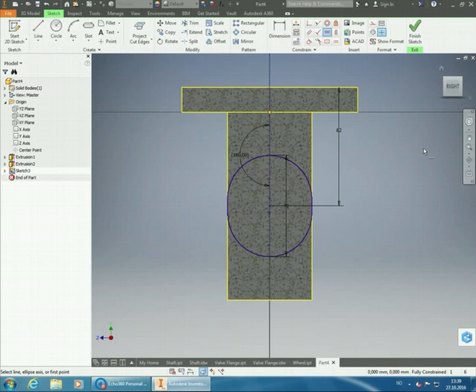Yeah, it's just 180 because I didn't want to put it with an auto constraint. So I just had to write in 180. As soon as I approached 180 with my mouse pointer, it jumped up to 60 degrees for some reason. So it's just a glitch with Inventor there.